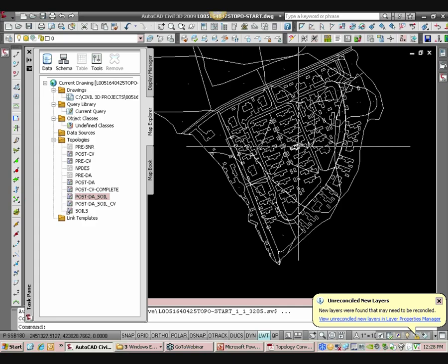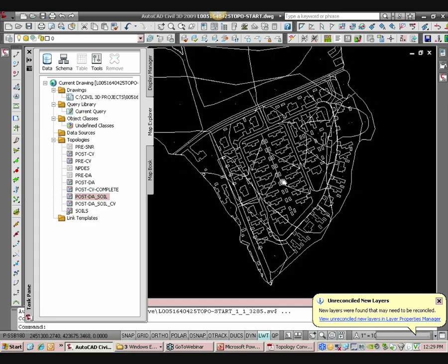And from this upfront investment, and we're doing the same thing all the time, we grade using 3D polylines in Land Desktop and now in Civil 3D Feature Lines to make our surfaces pretty accurate. Because then our profiles are accurate, our cross sections are accurate, our pipes are set right from the top surface, right? So we invested all that upfront time to get a huge benefit on the backside. It's the same thing. Let me just keep going.